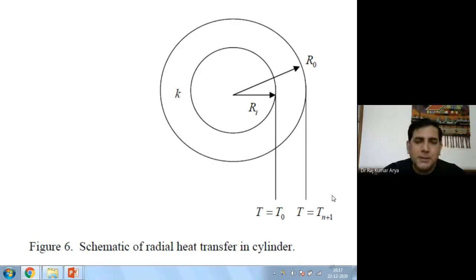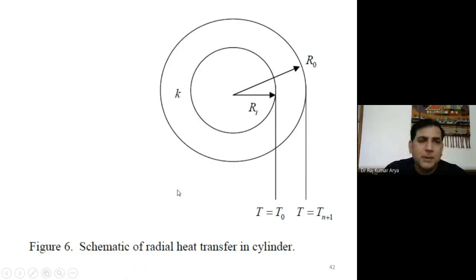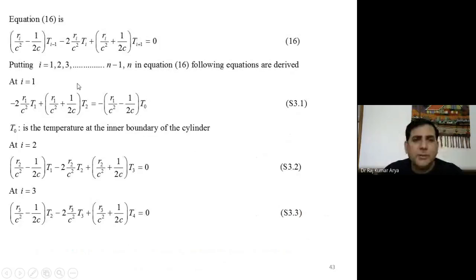Now what you have there, so now keep changing your i. Let's say your i equal to 1, you will get this equation there, and this is your boundary condition here, this one. So let's say we want to solve it for temperature boundary condition first. So let's say T naught is known, so that's what we have taken to the right hand side.